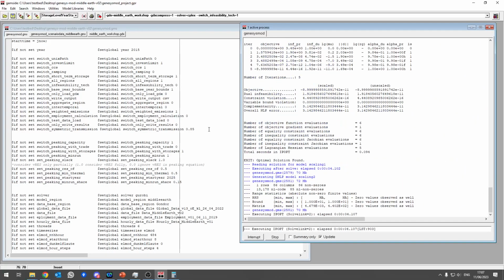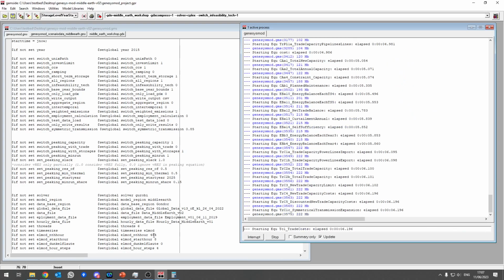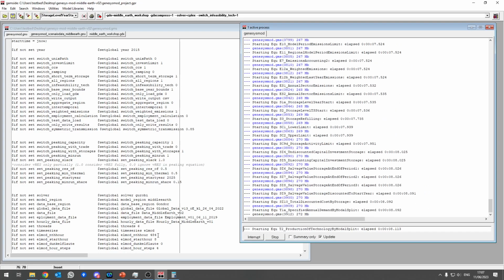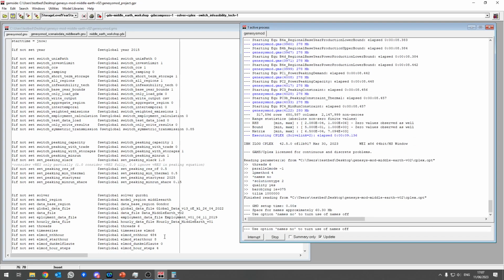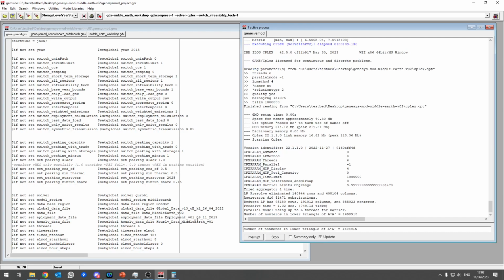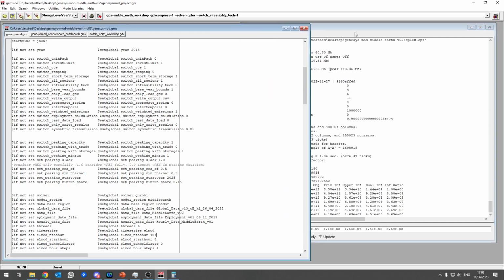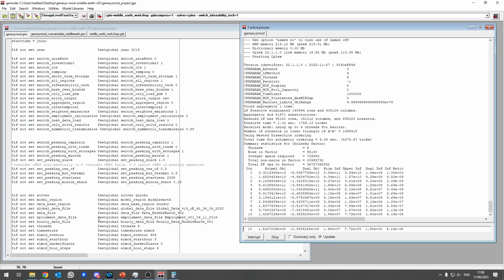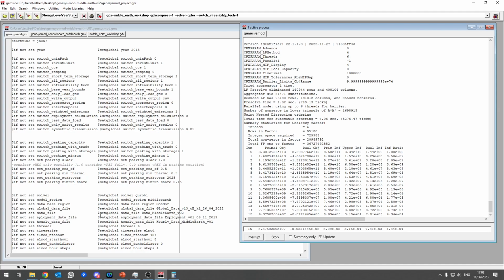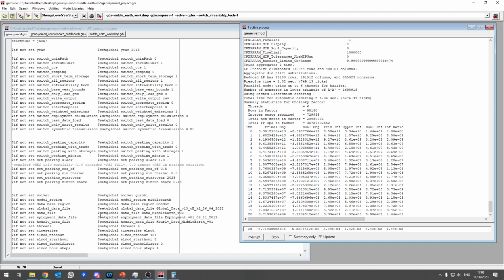And now we will run the model, but instead of with every 1000th hour, it will be every 485th hour or 484th hour. So now it will run again. But in the end, we've set the write output to CSV. So now we will actually get a CSV file instead of just the GDX file, and that we can use.